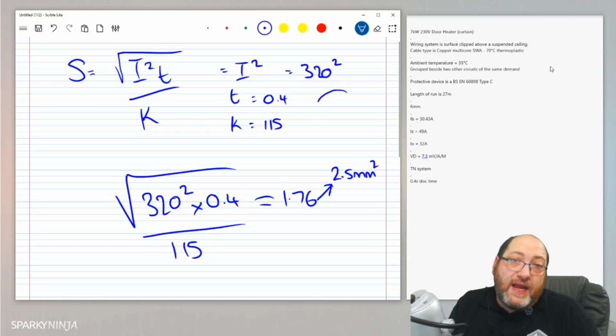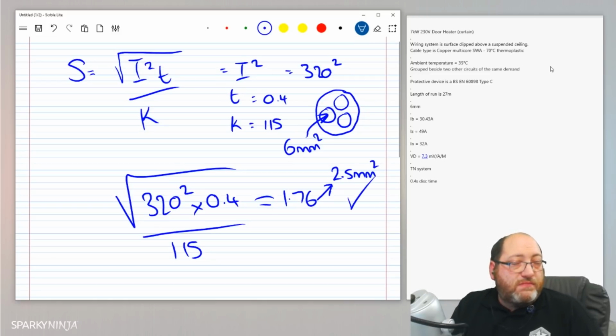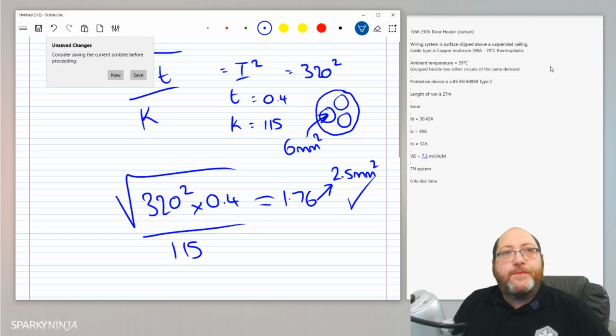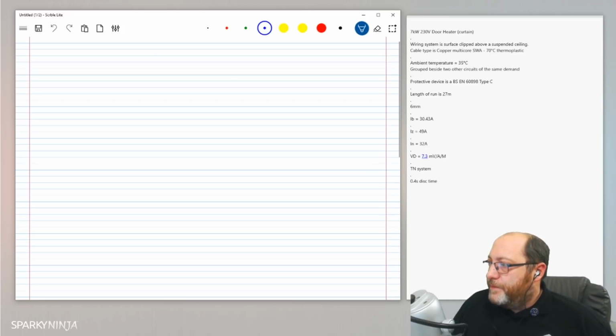Now it's most likely that our steel armor, being single phase, is going to be a 3-core, so it'll probably have within it a 6 mm protective conductor. So good. Alright, good. Just practice playing with the formula, practice punching in the numbers. What's next then? Well, maybe we should go back to chapter 41, to the Zs's.